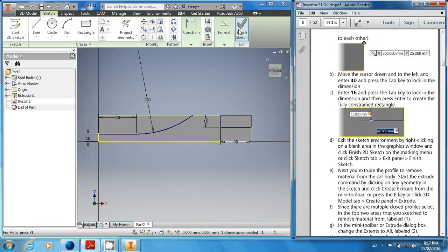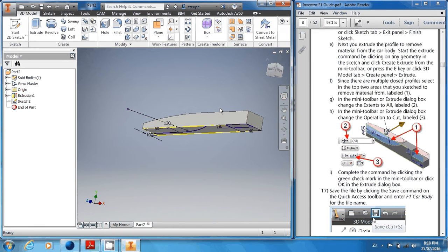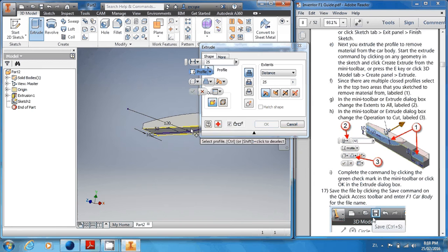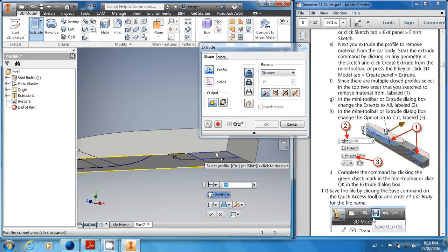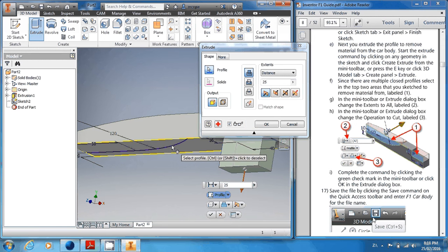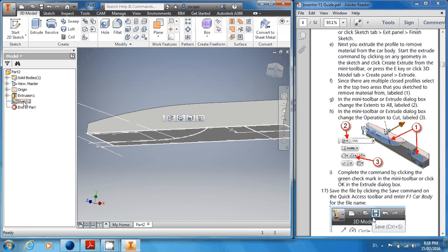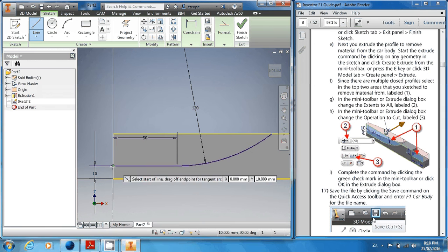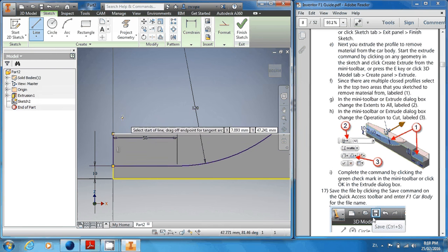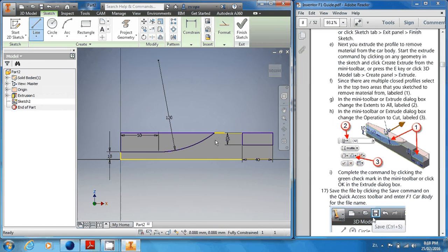Let's finish our sketch. Okay, use the extrude tool. Now we'll click each section. So we want to extrude this section and this section. Now this section is not working. So let's click cancel and let's go back and fix that. So double click on sketch 2 on the left. Okay, we need to add some more lines. So from this point to this point, click that point to this point. Now we got blue all the way around and blue here.